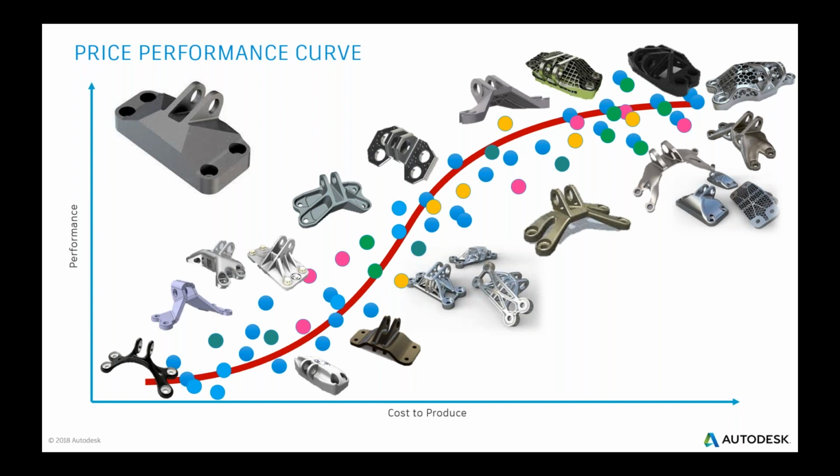So what we can do is give this sort of task to generative design. This would be a great model to say, look, I have constraints here. These are the 4 locations where I need this part to be fixed. It has to attach to something else. And this region up here, you can also make that a region that you want to keep because these are where your loads are going to be, and you define what those loads are. And then you just leave it up to the program to come up with the different designs and what it outputs using different manufacturing methods and materials.